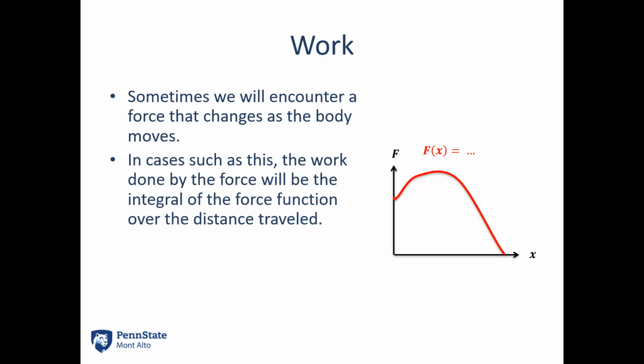In cases such as this, the work done by the friction force will be equal to the integral of the force function over the distance traveled, or the area under this particular curve. So work from x min to x max, minimum, maximum displacement there, and we just simply integrate the force function. All right, so all of those things are potentially part of the work done to any given body.